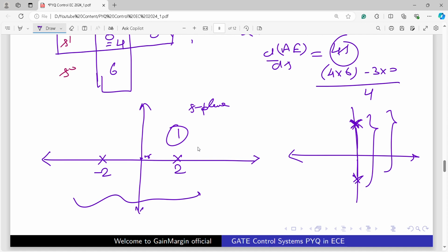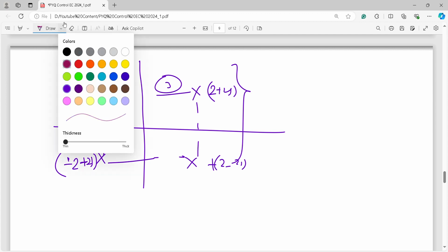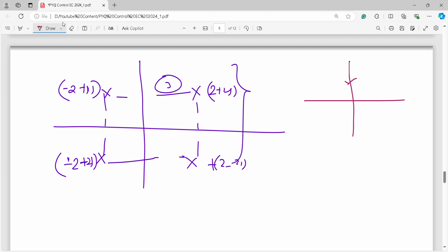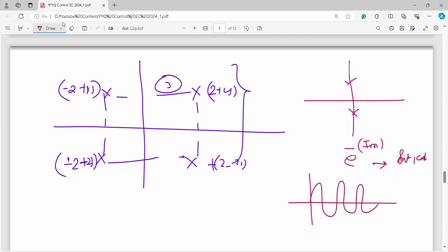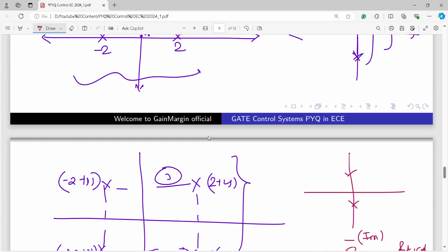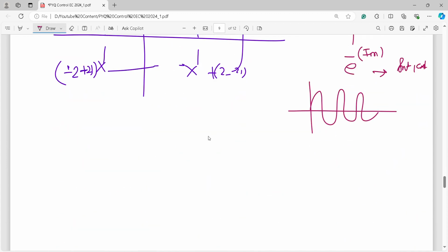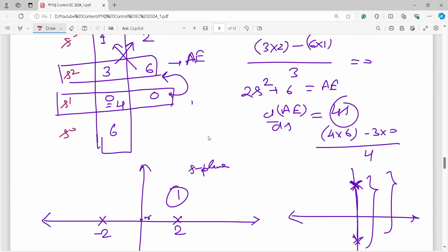When poles lie on the j omega axis, the imaginary terms will introduce sin and cos terms. So our system response would be oscillating. We need not find the exact response. We should only know whether the system is stable or oscillatory. So for the given question, the system is oscillatory.